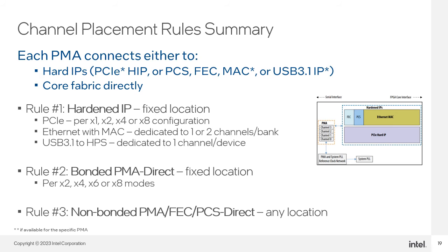Rule number 2 is about bonded mode. When you implement a bonded PMA, FEC, or PCS Direct, then that is in a fixed location, where you can implement the bonded according to the x2, x4, x6, or x8 modes. Rule number 3 is about non-bonded mode. In non-bonded case, PMA, FEC, and PCS Direct can be in any location.